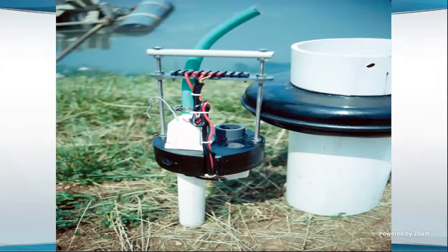So there should be an effort to do several things. One is match the motor that's running the aerator to the actual aerator load. That's a particular problem in Asia where they use those foreign-made aerators. They don't match the motors to the load. Sometimes they've got a 14 horsepower little diesel engine sitting up there running a load that probably needs a 3 horsepower motor to turn it. And in other cases, they may overload the motors. But there needs to be a lot more effort to match the energy use with the actual need for oxygen in the pond. That would reduce this high energy requirement for fish production.